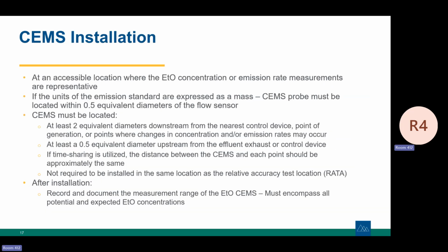Installation. This is language around making sure that you're putting your sample points in places that make sense. The rule does allow for sharing sample points in an instrument. As long as you meet certain requirements, you can have multiple sample points in an instrument. Make sure they're approximately equidistant apart, and that you're looking at all possible concentrations in your process.